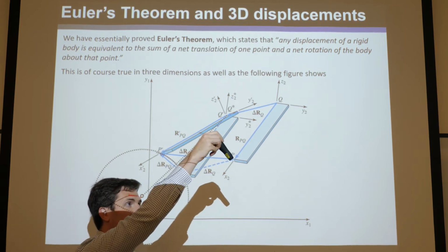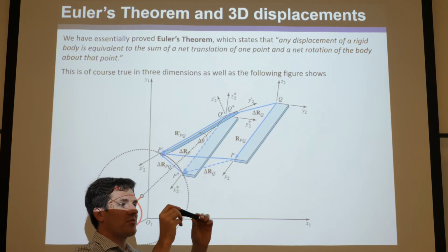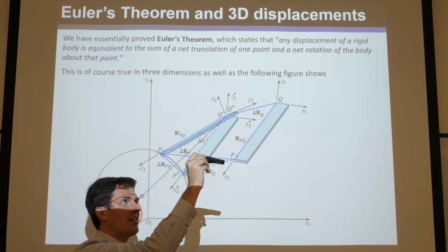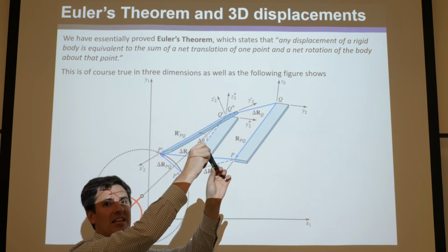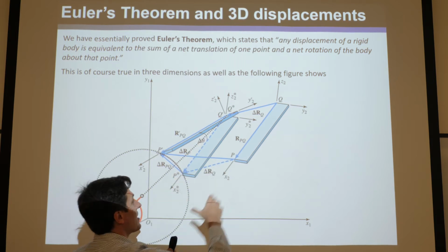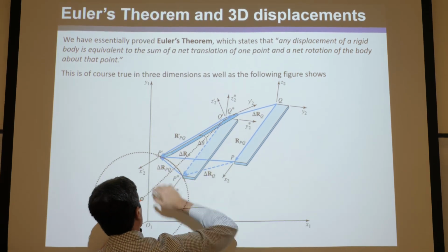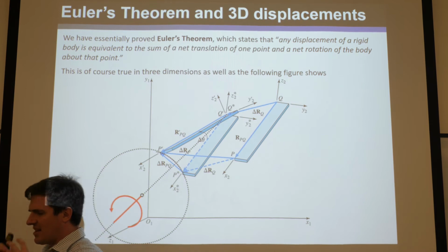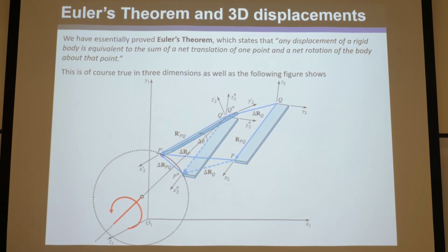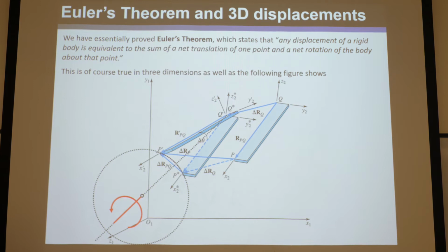to get from there to the original, there was always some pure translation of a point, and then some rotation about that point to get to that configuration. The translational component is this delta, and then the rotation is about this to get to there. That's the point. And again, it's not about a path. We don't care about the path it takes. It's all relative to which points you subtract from what. But you can break any two positions down into a translation and a rotation about the point that you translated. Understanding those vectors and the differences is going to be really key.